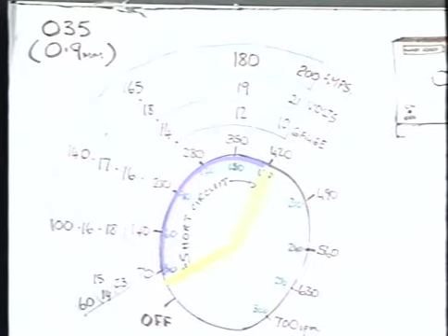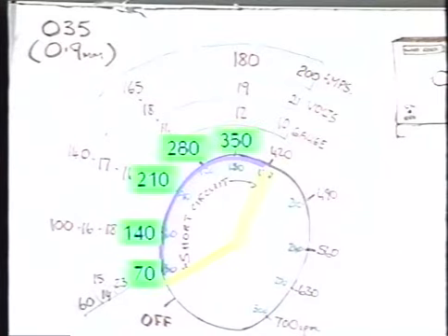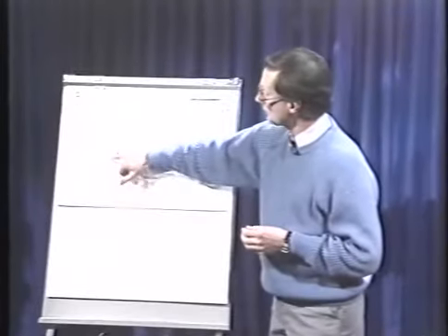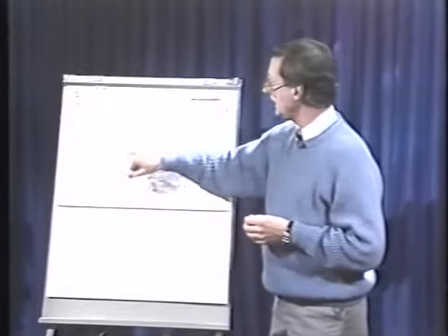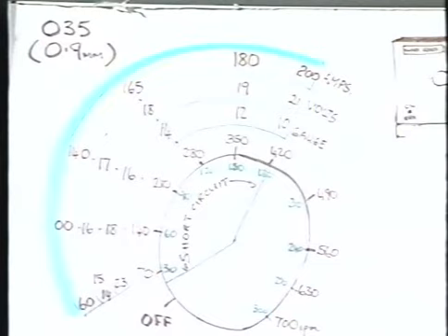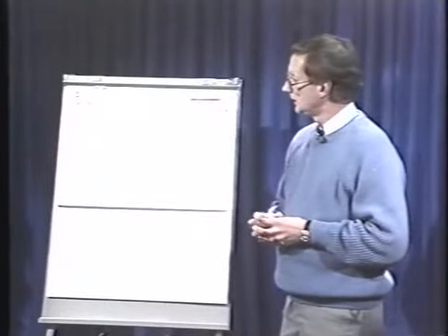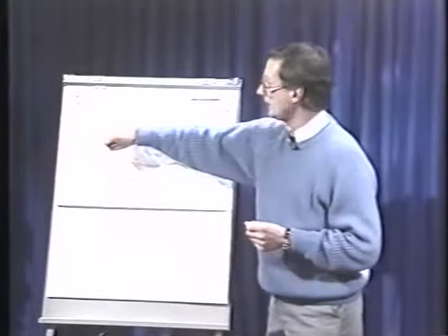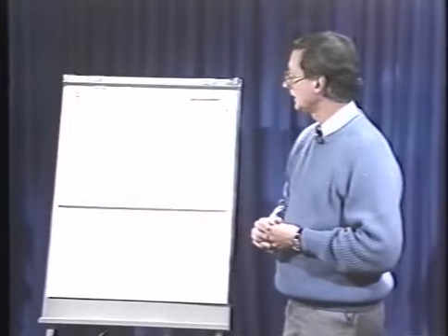The green marks on the wire feed control here are millimeters per second, and we have, as you can see, 70, 140, 210, 280, 350, 420 IPM. It's inside this wire feed range of 70 to 420 IPM that we draw in current around 50, 60 amps to around 200 amps. This amperage range is the range for short circuit welding.